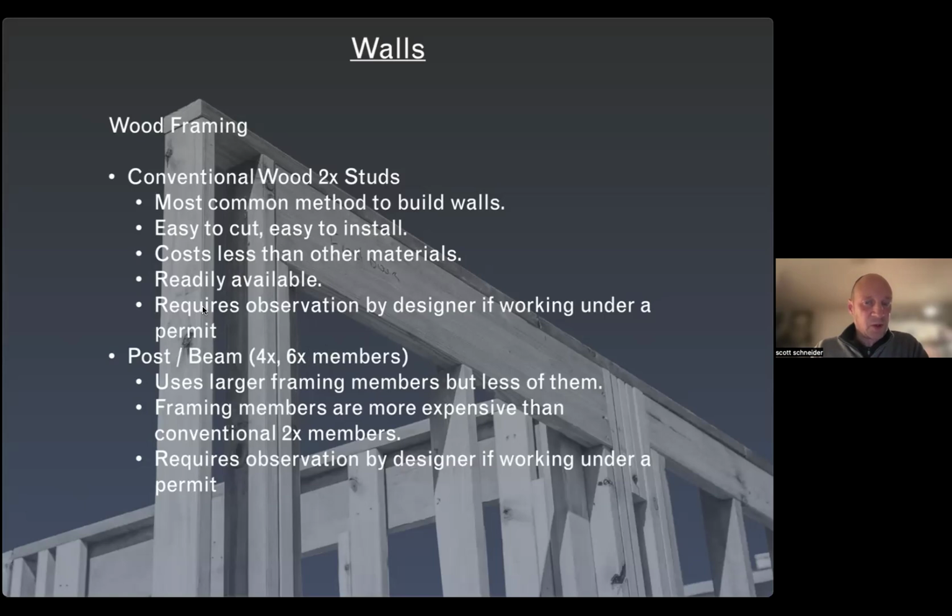If you have to get a building permit, framing actually requires an observation. Post and beam, you're using larger members, but less of them. They're a little bit more expensive than the conventional 2x members. And again, they require observation if you're getting a permit.